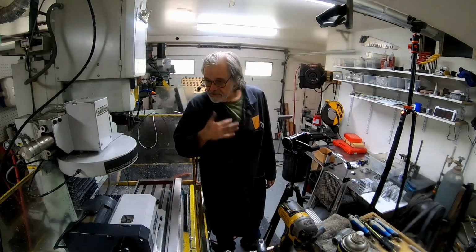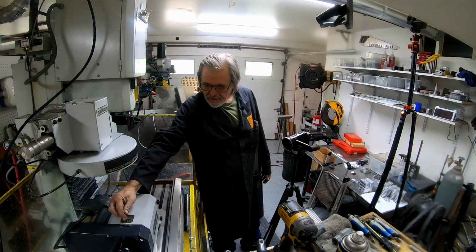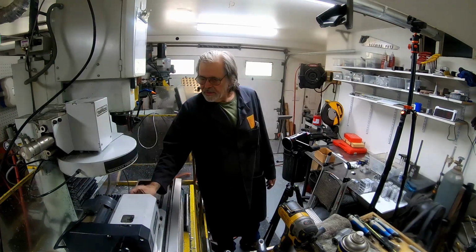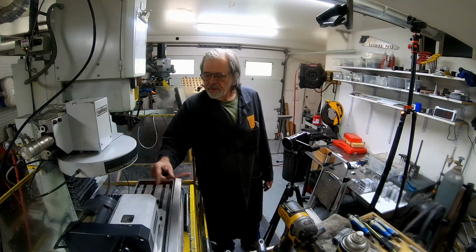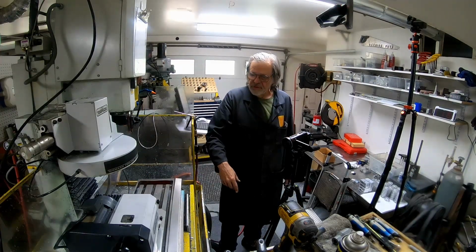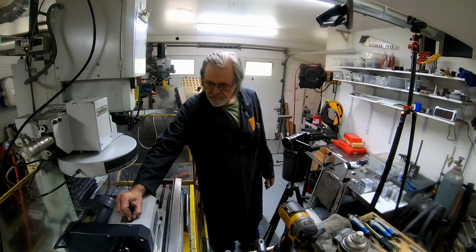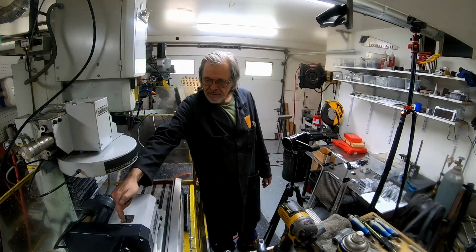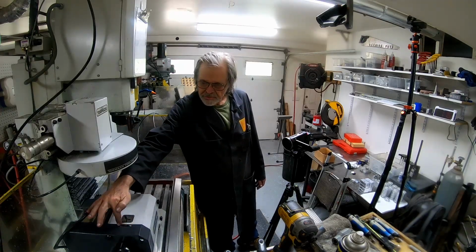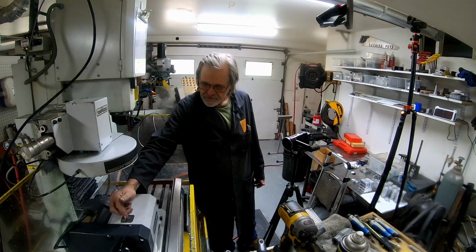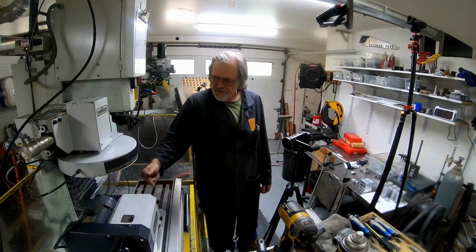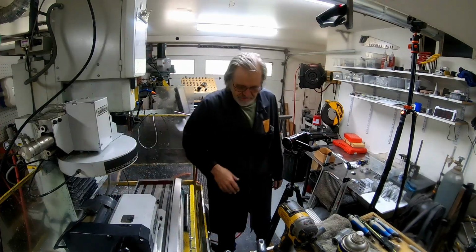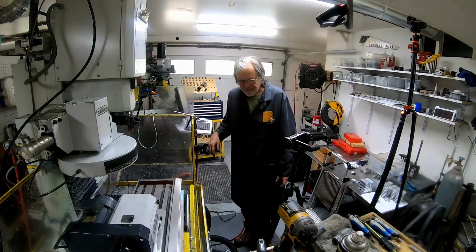Evidently, somebody thought it was a great idea to have a little locking lever here, so you can use it as a kind of somewhat crude indexing head with 15-degree increments. If you put the little locking thing in, it'll lock at a variety of different 15-degree increments, and there's a little dial over here that shows where it is. And of course, the gotcha is if you turn it on and forget that it's locked, well, the motor's going to slip and it's going to mess up your pulley and mess up your belt.